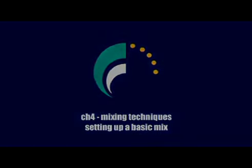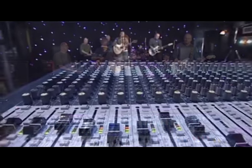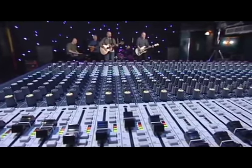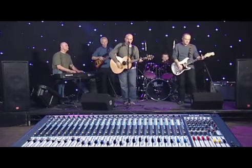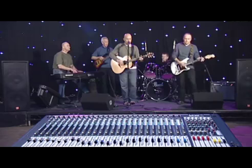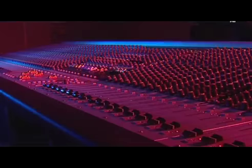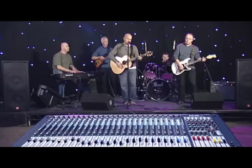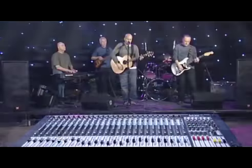Mixers can only work with audio that's at the right level. The input gain control boosts or cuts the incoming signal so that it falls within the range of levels that the mixer can cope with. All electronic devices, including mixers, produce a low level of electronic noise. Well-designed mixers minimize the noise problem, but you can never get rid of it completely. So what you have to do is make sure your mix is properly set up to get all the audio you want in the final mix and as little noise as possible.